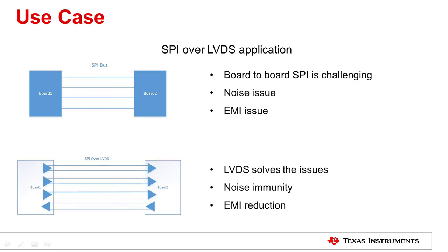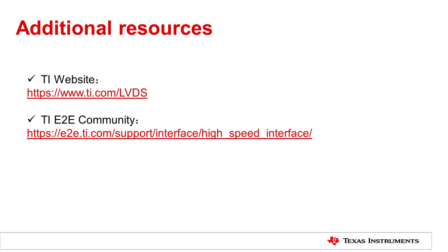If the application is in noisy environments, a wide common mode receiver, such as SN65LVDS33, can be used to combat harsh conditions. TI offers a wide range of LVDS drivers and receivers that are suitable for different applications. For the full portfolio, please go visit ti.com/LVDS.